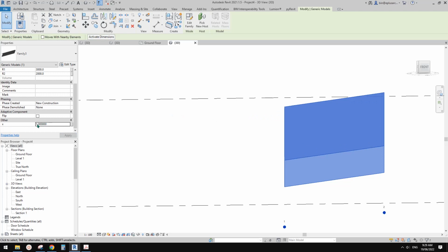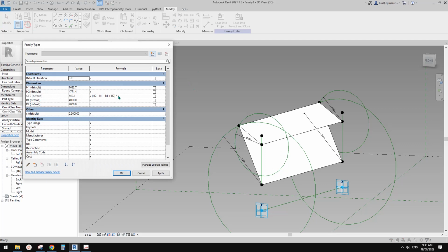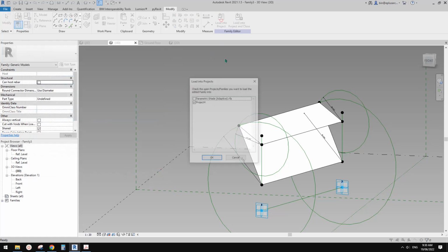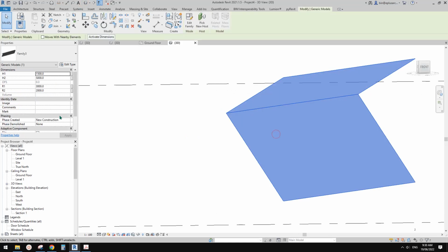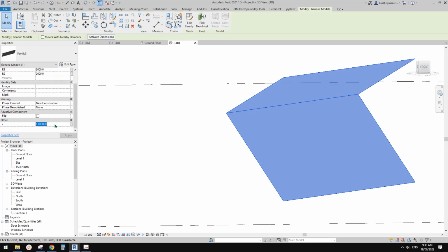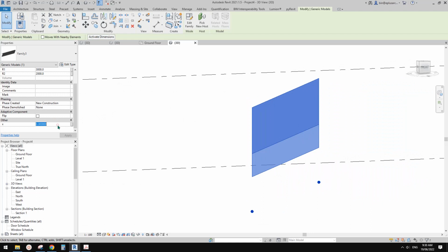And if you want, maybe you think 0 should be vertical, so you can do it in here. So maybe instead of times x, we can just use times 1 minus x. I think this should work. Load this back. Go to 3D view. So now when it's 1, it's open. When 0, it's closed. Yeah, that makes more sense. Yeah, this is it.